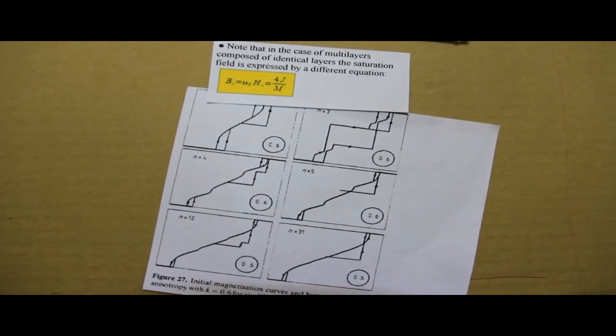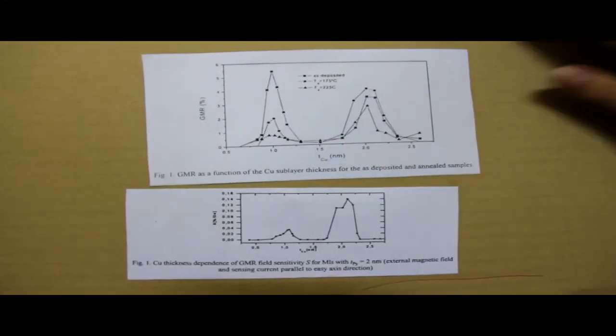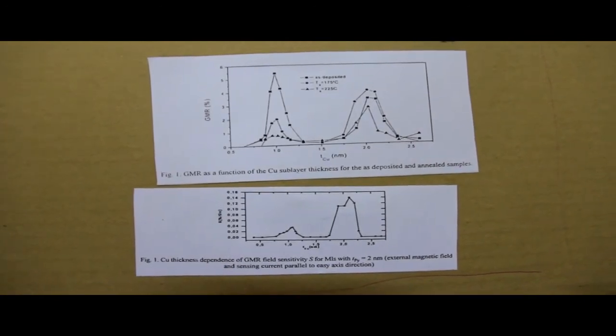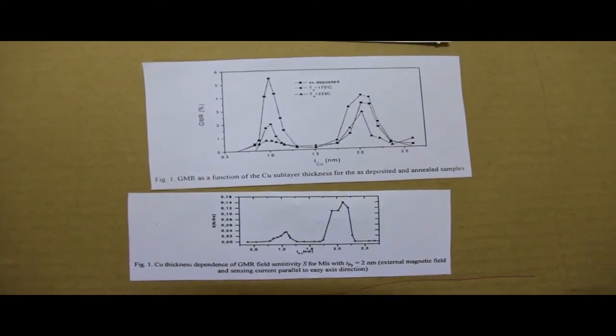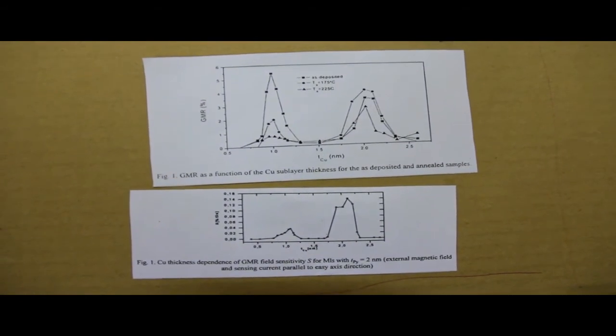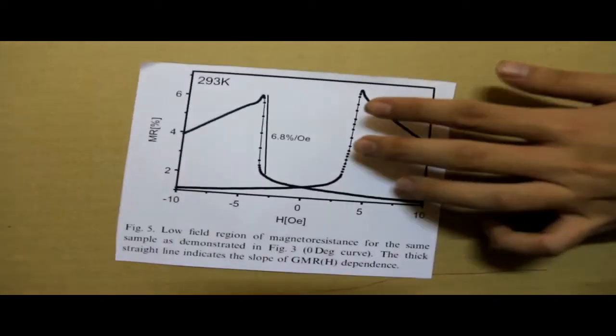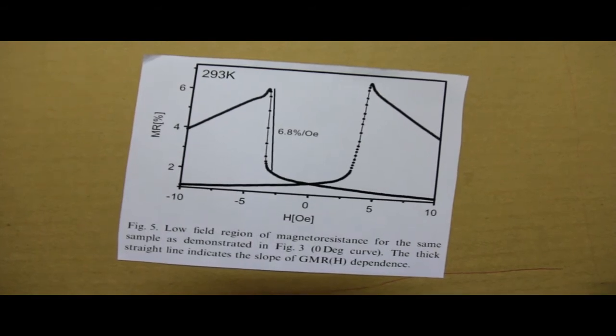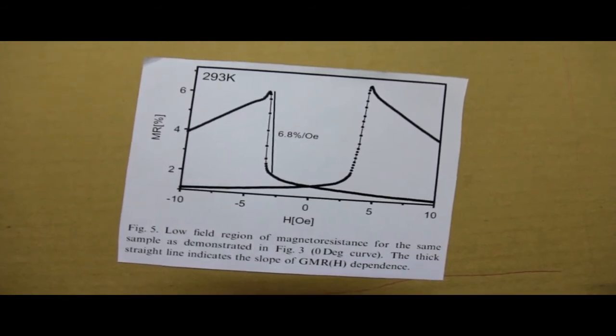If the anisotropy is present, shapes of hysteresis loops can be complicated and strongly n-dependent, at least for small n. For the field sensitivity of magnetoresistance, we know that the RKKY-like interlayer couplings strongly decrease with the spacer thickness Ts. The saturation field of the GMR effect depends consequently on Ts, but the GMR amplitude decreases with Ts.